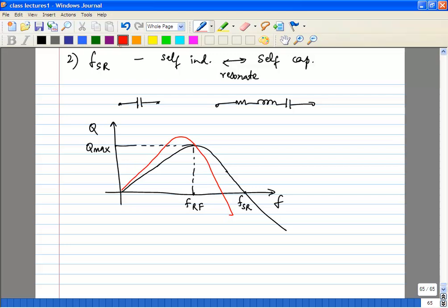So you can choose any kind of inductor topology you want. There are different kinds of inductors; we covered one or two in class. If you want to do some extra research and read some paper and come up with a newer structure which gives you better Q, perfectly fine with me. But I'm going to give you a given area, and you need to maximize Q at a particular frequency. So you'll be choosing different architectures, varying the trace width, varying the spacing and so on in the software,